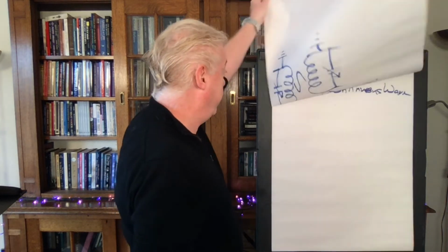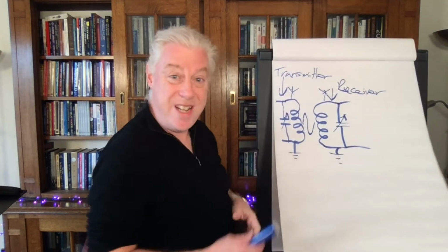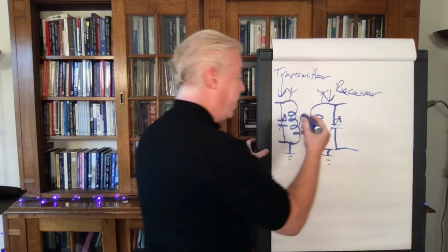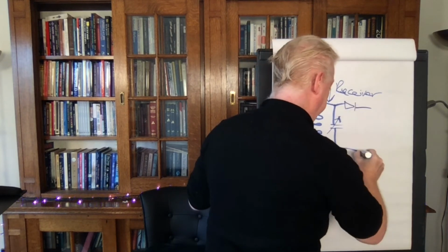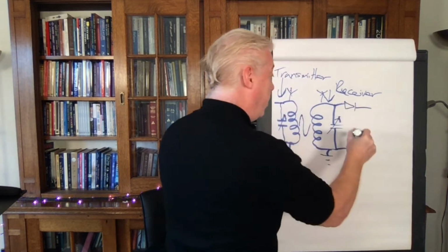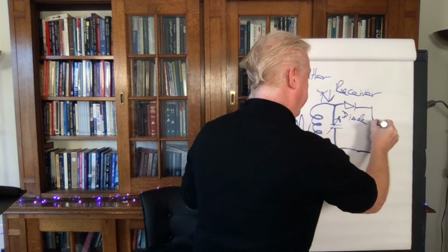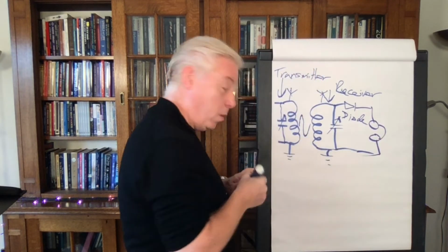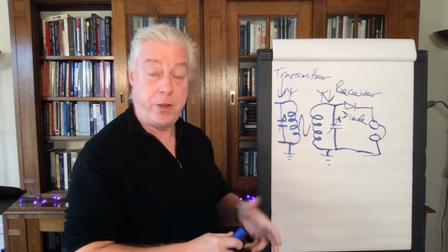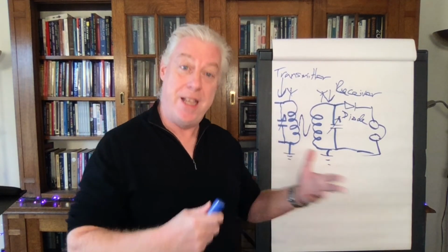And what we can then do is decode that at the other end by putting a diode in the circuit, and then literally we could put a pair of headphones here, and with no power, no battery, no amplifier, we can actually hear the radio broadcast.